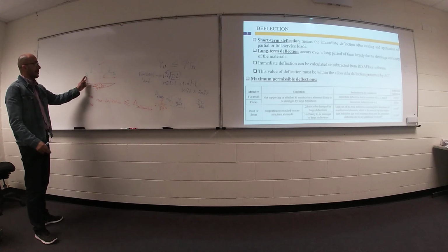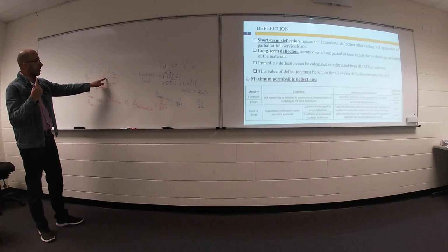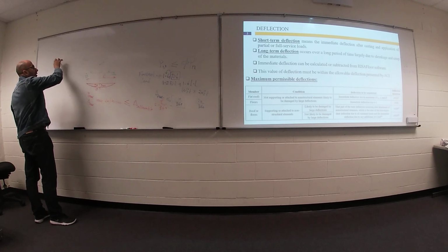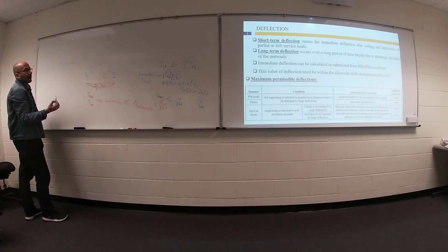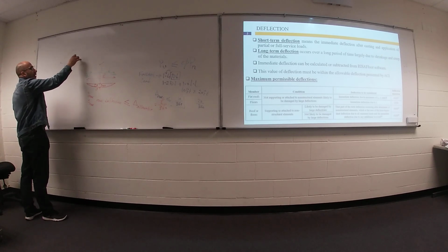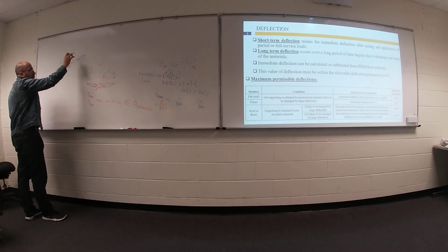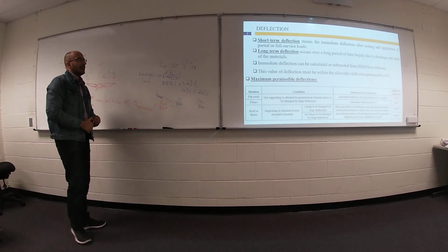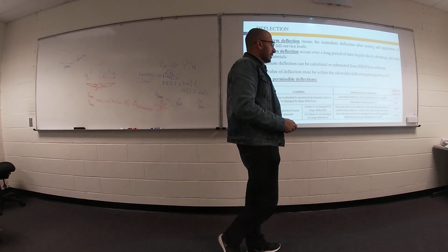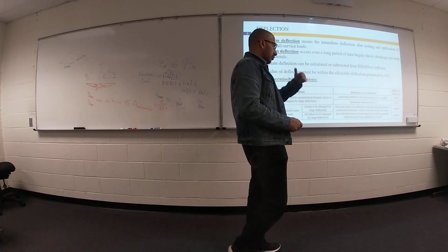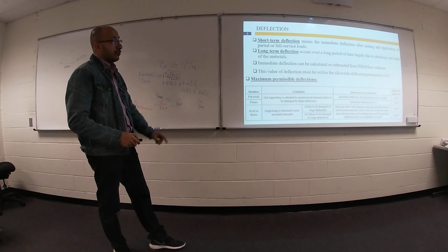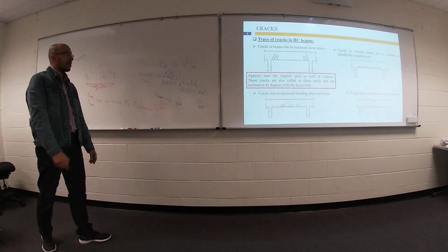If you are talking about a beam, we have only one distance or one span, your L. But if you are talking about a floor, we are talking about an area, so we have a longer and a shorter distance. Maybe both of them are equal. Anyway, keep this one in your mind: L over 360, we will use it later, against live load, and your live load is surface live load.